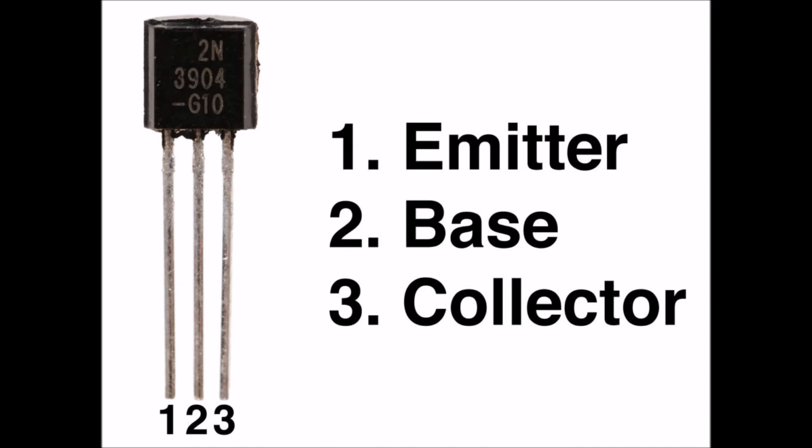Fluctuating DC flows through R1, and a fluctuating voltage therefore appears across it. The AC part of this voltage passes through C1 to the output. Because the output follows the emitter current, some engineers and technicians call this arrangement an emitter follower circuit. The output wave of a common collector circuit appears exactly in phase with the input wave.